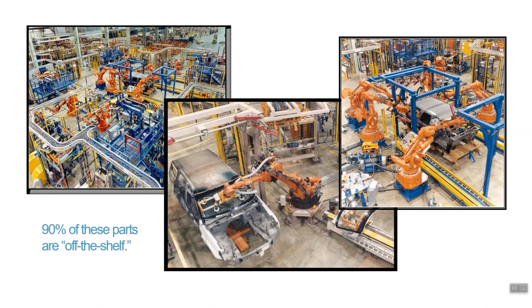So the main idea of thinking in standard parts is to choose certain parts that you standardize as a company ahead of time, and then decide up front certain parts that you're going to use in the design, and then design around those parts instead. So if you're able to choose 10, 15, 20, 30, 40% of parts at the beginning of a project that you're going to use, and then custom design around those parts, you're able to automatically build reuse in to your design rather than designing everything and then trying to fit those parts in after the fact. Just build some of that reuse in when you choose the certain parts to use up front.